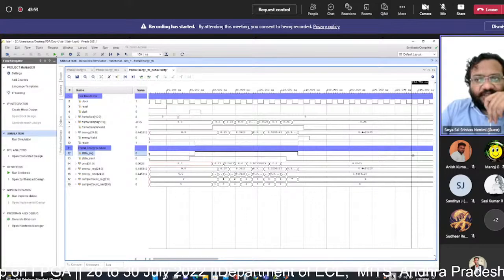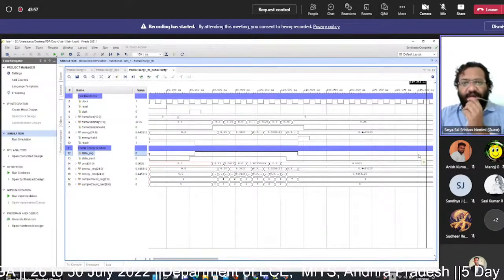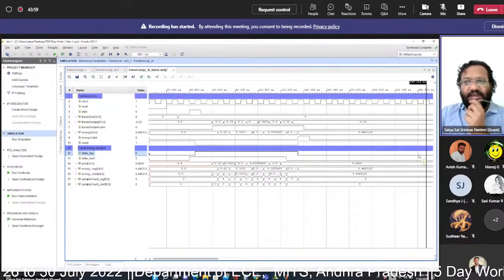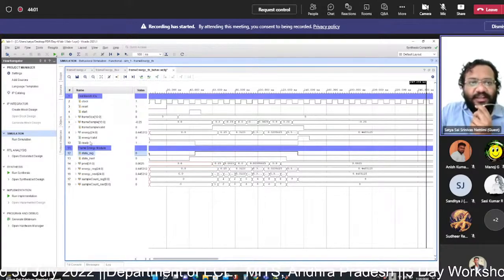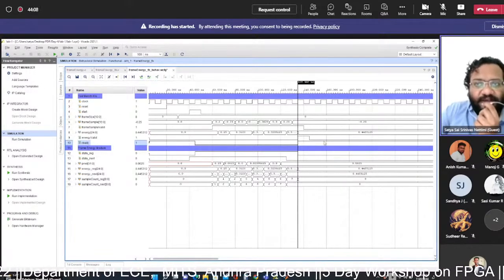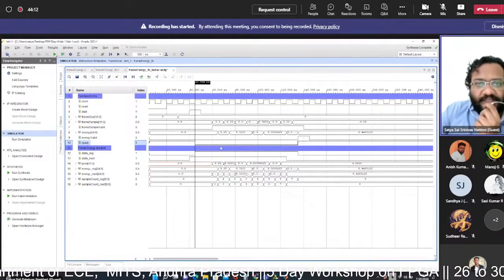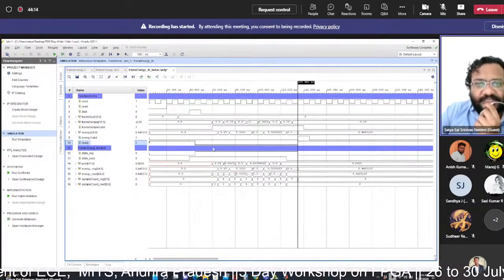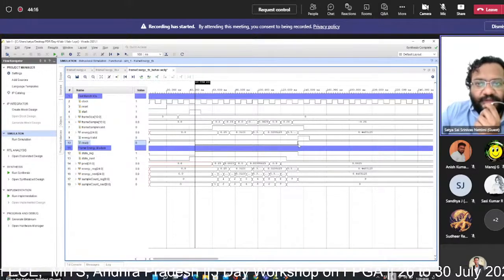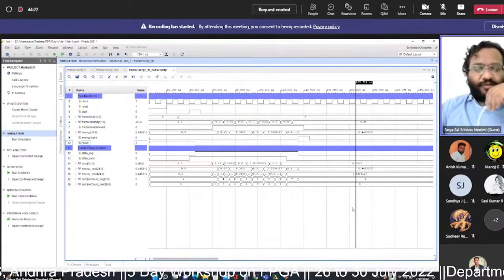So no further state transition is happening, and the FSM remains in the S0 state, which is the idle mode. When it is in the idle mode, the ready should be at logic high. So soon after the FSM enters the S0 state, the ready output is made logic high. While it is in the computation phase, that is the S1 state, the ready output is logic low, that you can see over here. So this is how we have designed our module.